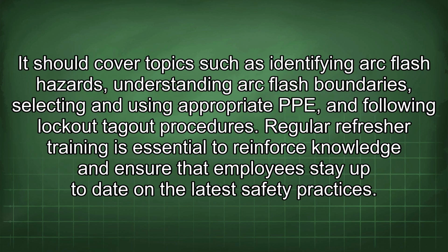It should cover topics such as identifying arc flash hazards, understanding arc flash boundaries, selecting and using appropriate PPE, and following lockout-tagout procedures. Regular refresher training is essential to reinforce knowledge and ensure that employees stay up to date on the latest safety practices.